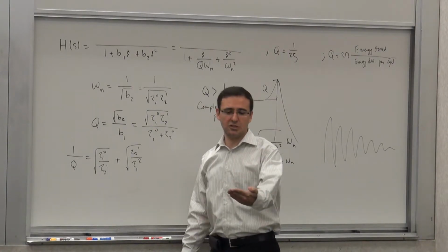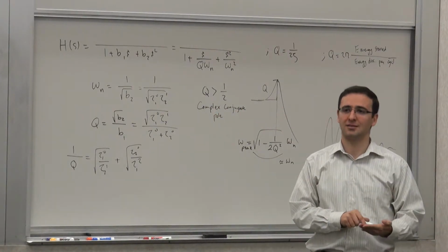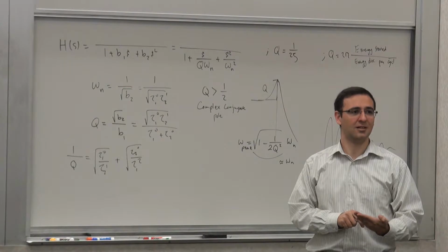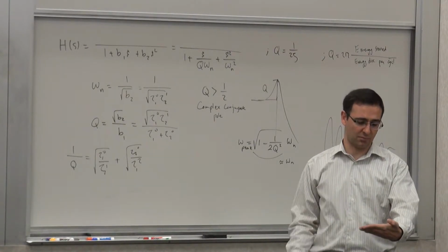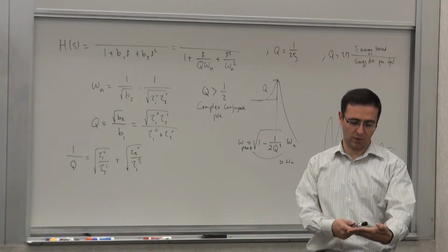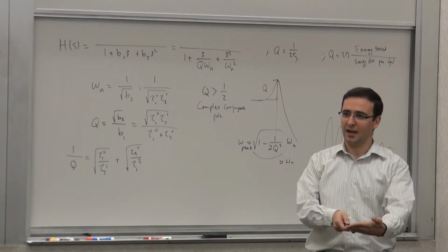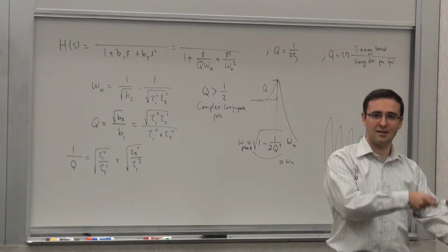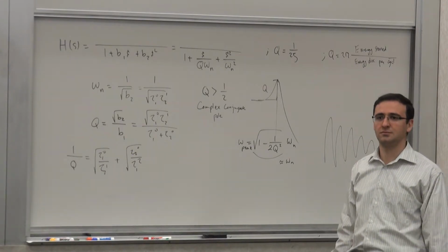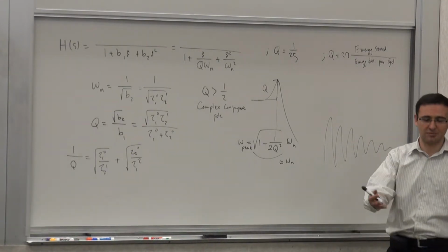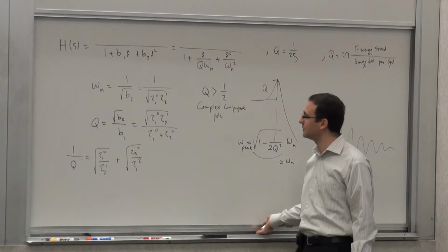And a lot of times you don't need to calculate this accurately. You don't need to calculate all the terms of V1 and V2, because when you're doing it numerically, you can tell which term is dominant. You can see, okay, I have 5 terms in V2, but I don't need to calculate them because 4 of them are really small compared to this one. So I calculate that one, and then the 2 from V1, and then calculate that ratio. It becomes a back of the envelope calculation. You just need to be clever about it. You need to keep your eyes open.